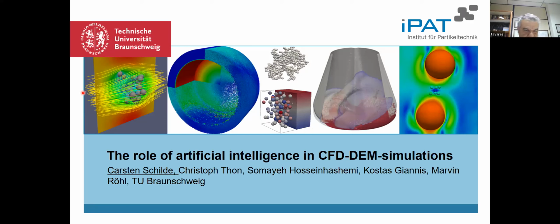We are as well here, because my comment is that, yes, in the coarse size range, we have been very successful, I'd say, when we deal with very large grinding media, like 25 millimeters, 30, 50 millimeter balls with sub-millimeter size particles. Assuming that you have most of the time down to a monolayer stressing condition, using more or less the division from Karl Schönert's stressing volume.